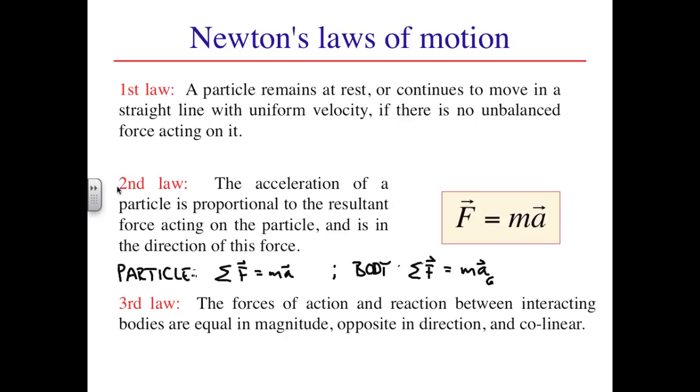The equation describing the linear motion of the body looks just like that for a particle, except the acceleration refers specifically to the acceleration of the center of gravity. So for instance, looking back on our illustration with the furniture, we would be looking specifically at the acceleration of the material point at G that's labeled in that figure.